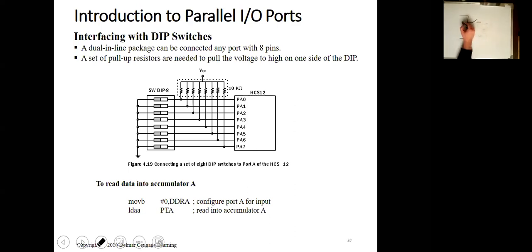If it is connected to PB0, port B, pin number 0, and we want to input a 0 or a 1, and we connect it to +5 volt, then when the switch is closed and we read this pin, we read a 1 in the PTB register. Specifically, bit number 0 will be set to 1.